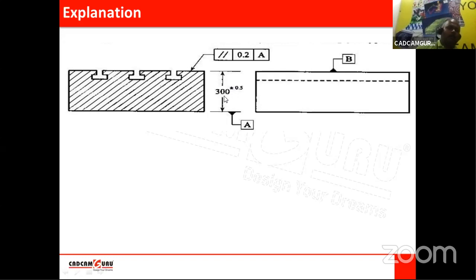It means the range of this dimension is from 299.5 to 300.5. When there is a plus and minus tolerance, it is called bilateral tolerance, and bilateral tolerances are mentioned for general purpose dimensions.